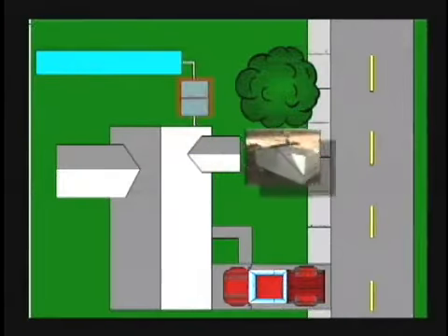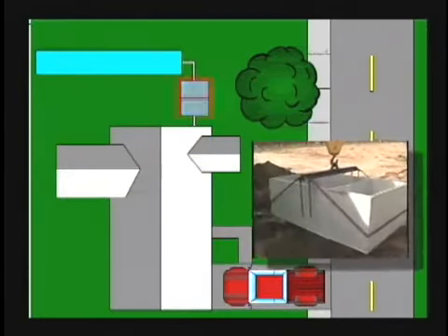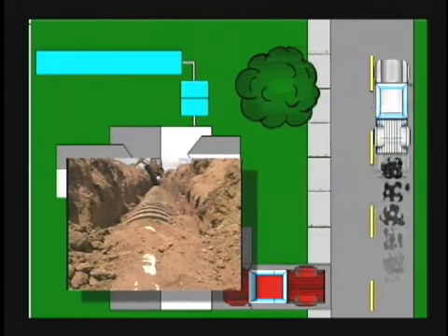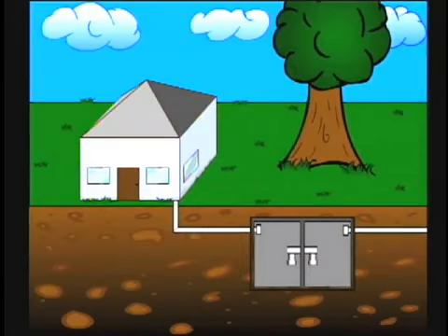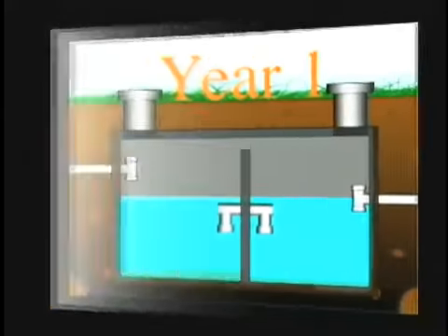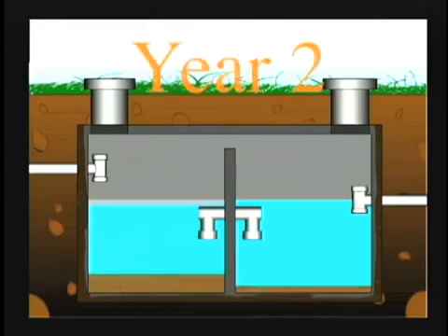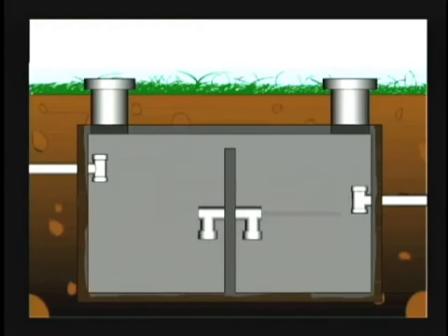There are two main parts to your home wastewater treatment system. The first part is the septic tank that removes solid material. The second part is the drain field that disposes of the wastewater. The septic tank is usually divided into two sections or compartments. The first compartment removes grease and solids that will plug up the drain field and cause it to fail quickly. It is critical that the tank not become overfilled with these waste solids. This is why the septic tank serving a home should be pumped every 2 to 5 years.